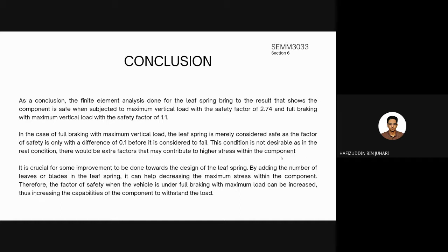In the case of full braking with maximum vertical load, the spring is merely considered safe as the factor of safety is only 0.1 above the point where it is considered to fail. This condition is not desirable, as in real conditions there would be extra factors that may contribute to higher stress within the component.